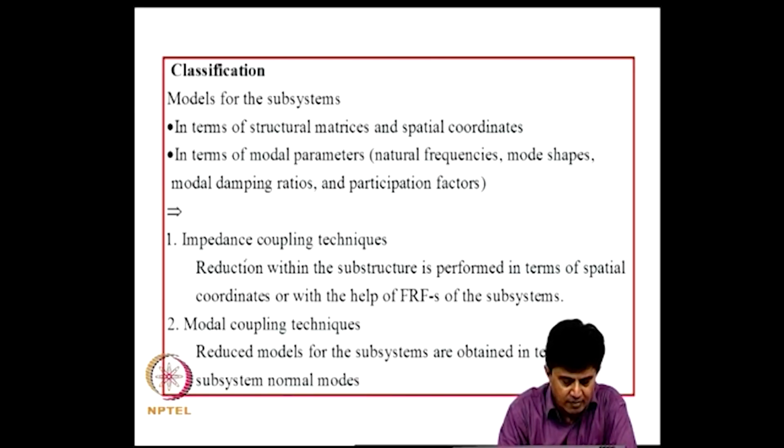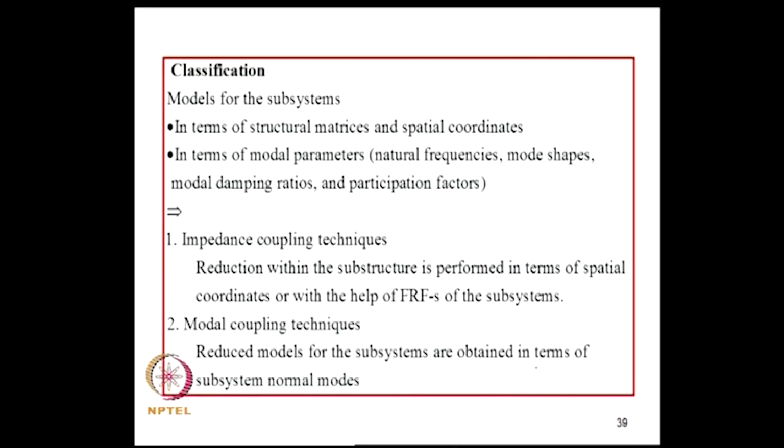In one scheme of classification, we classify these coupling techniques as impedance coupling techniques and modal coupling techniques. In impedance coupling techniques, reduction within the substructure is performed in terms of spatial coordinates or with the help of frequency response functions of the subsystems. We do not use modal information. In modal coupling techniques, reduced models for the subsystems are obtained in terms of subsystem normal modes.